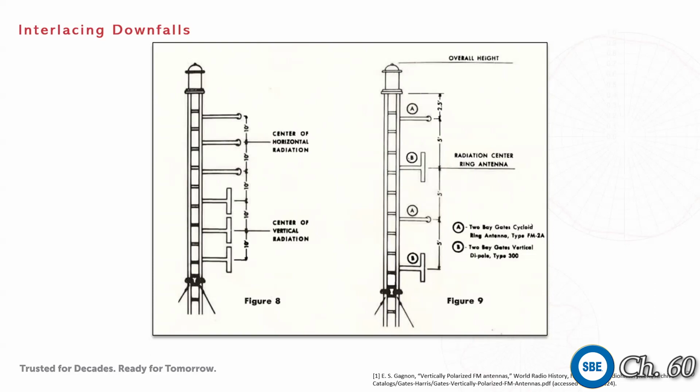So for each layer, especially in the low and the mid band, your antenna is going to get pretty high. But more importantly than that, you have two main beams that are coming off of this, your horizontal and your vertical, and there's only one spot, basically just directly straight out, where the axial ratio or the reception difference between the horizontal and the vertical is the same.